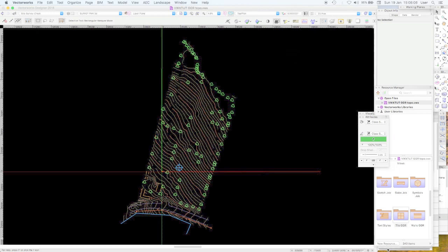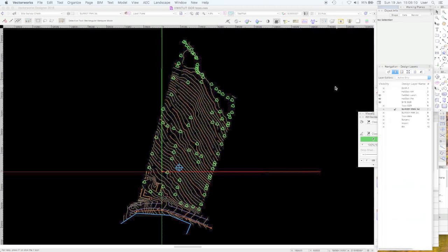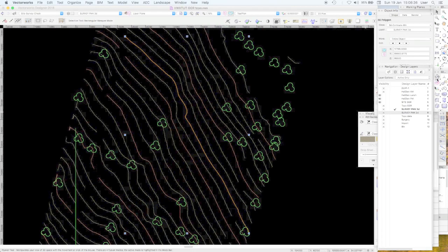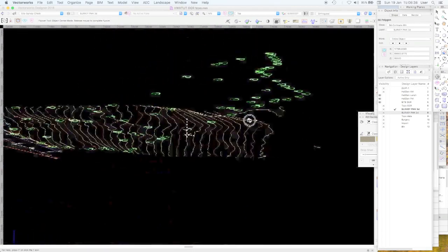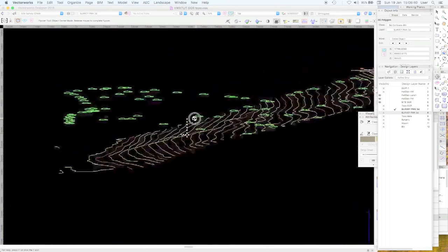in this case where you can see I've got two layers: survey 3D and survey 2D. There's a reason for that. First of all, if you're lucky, the AutoCAD survey file, its contour lines will have 3D values, which is great because it's a 3D drawing.